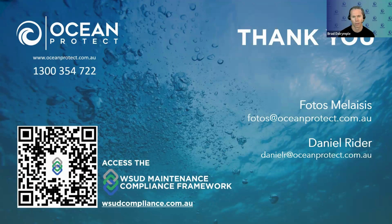Any other further comments on that one? Oh, yeah, I think the asset owner could be demonstrating environmental harm to downstream waterways, and that's dependent on a range of factors. Site-specific conditions, I think you want to look at the annual rainfall for that catchment, the catchment area, site application, commercial, industrial, residential, traffic patterns. All these things will contribute to pollutant load generating factors, and based on those site-specific requirements, you can tailor a maintenance program to suit. And so the cleaning frequencies would be subject to that site.